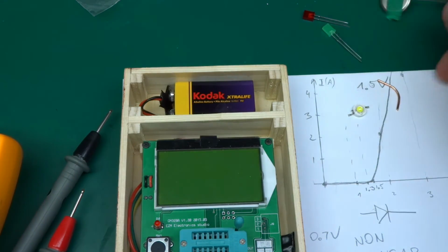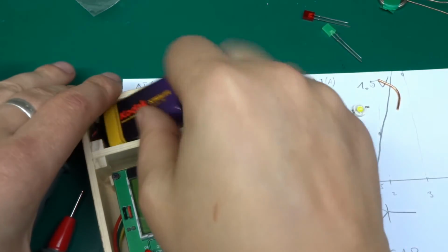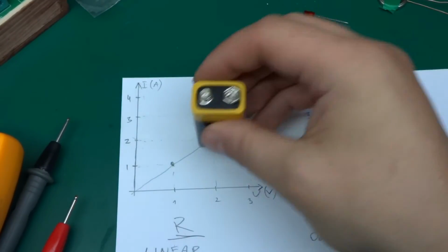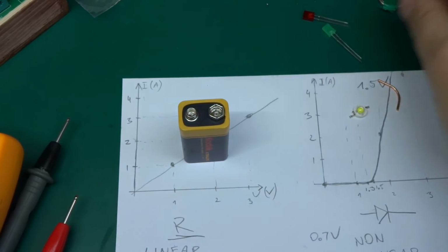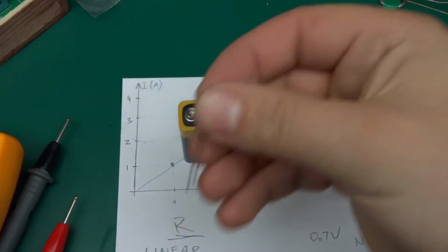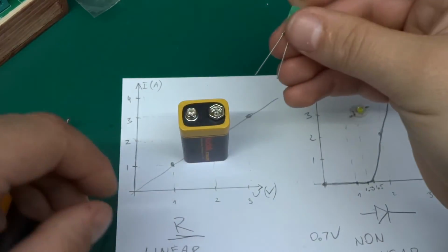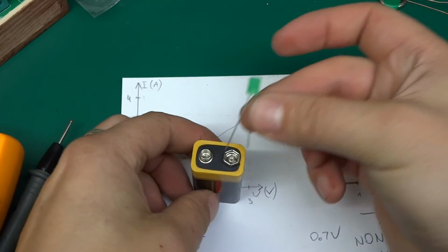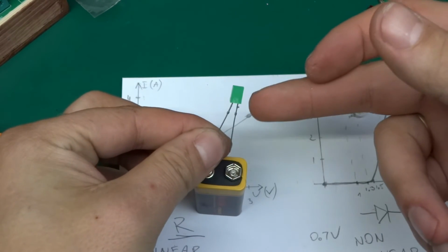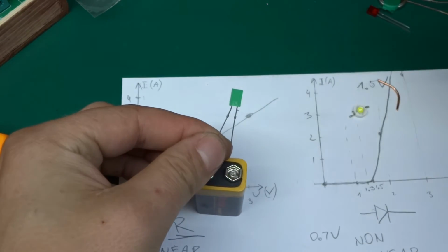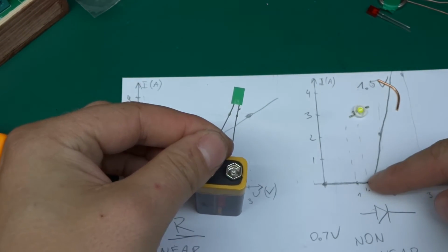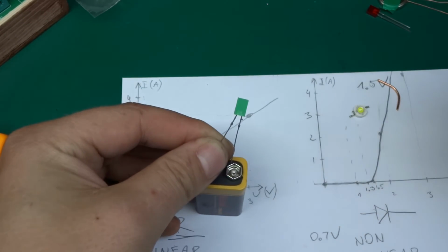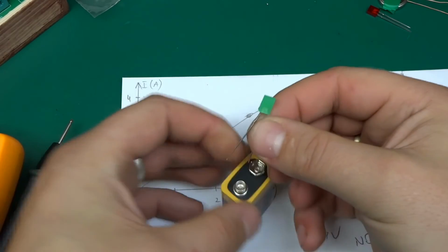Now you might be tempted to use something a little bit higher, let's say 9 volts, if your LED is not working and you think, what could be happening? So let me show you what would happen. If you put it across 9 volts, we know the forward voltage of this was what, 1.8 or 1.9 volts, and we're going to put across, say, this is slightly dead, this battery, maybe 8 volts or so. So let's see what will happen.